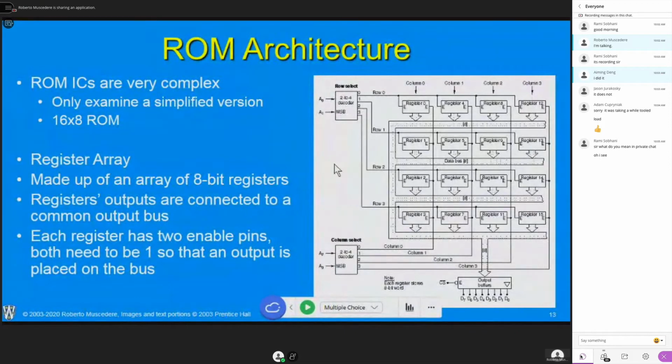Now, do keep in mind that when you go and buy a memory chip, we're not talking a few bytes as we are seeing here, with this 16x8. They can be in the gigabytes of memory. So there's certainly a lot of words in there, and we have to be able to access them and say which one is going on at once. And this is what really slows down memory. This is why DRAM is kind of slow. The speed of DRAM goes down as the capacity increases, because we have to figure out again where is that thing you want to read and write from? And that's what takes the longest time.